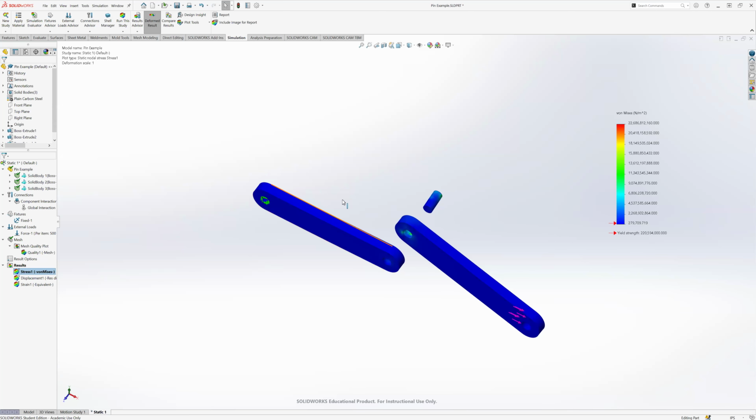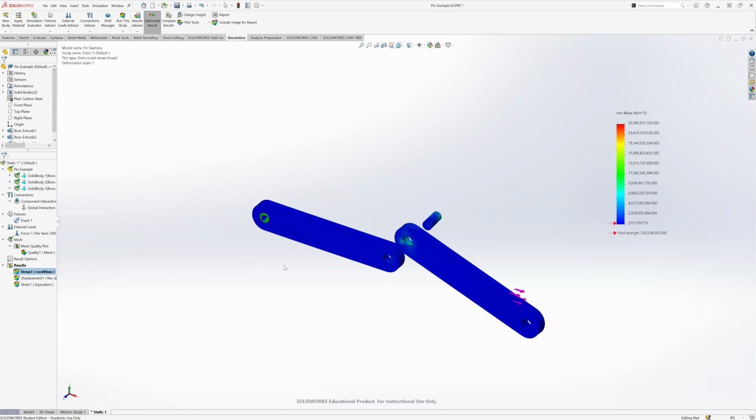So then we're going to have to go back to the drawing board with our fixtures and try to play with it a little bit more. But if you see something like that, that is a good indication that your fixtures are not working 100% correctly. So let's go to our fixed constraints. What I'll try to do here is, let's go to our fixed, and the first thing I'll do is go and hide this stress plot real quick. So let's go here and hide.